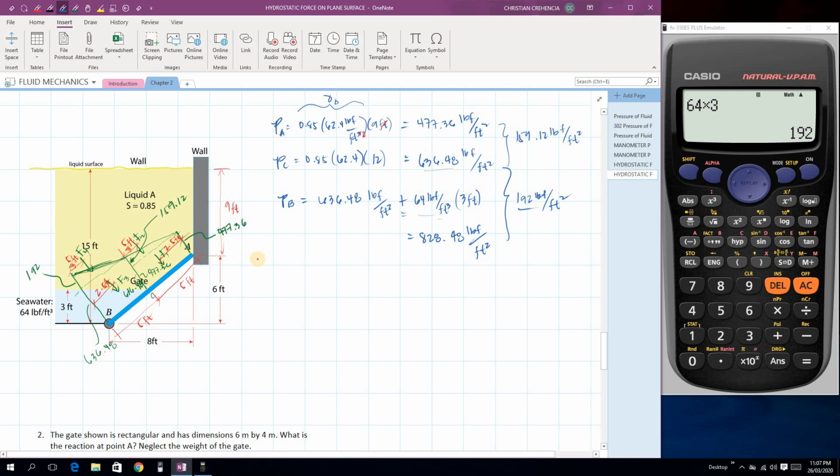So isosolve na lang natin yung value ng F1 hanggang F4. So F1 is yung volume na itong rectangle. So ang height natin dyan is 477.36. So uniform pressure. This is pound force per square foot multiplied by area. So kalahati lang yung area na kino-consider natin, no? So 5 feet, then yung width nitong gate natin is 5 din. So 5 by 5, then square foot. So cancel lang yan. So pound force yung matitira. Okay.